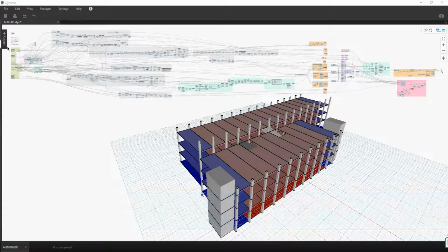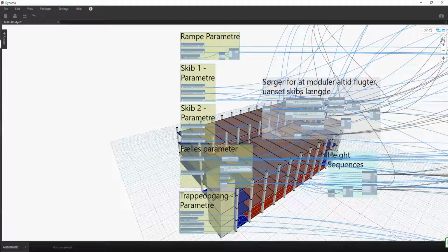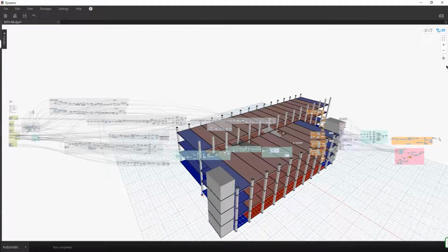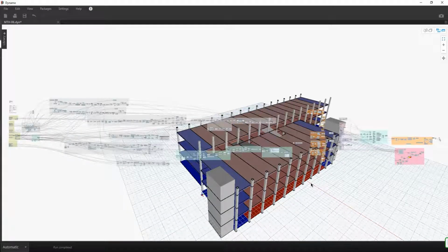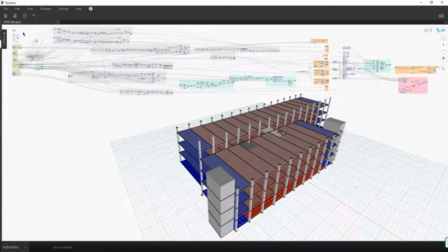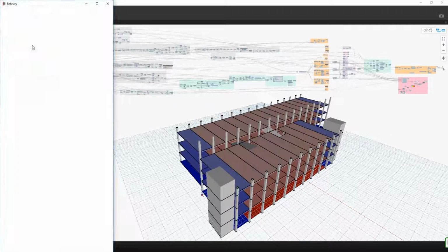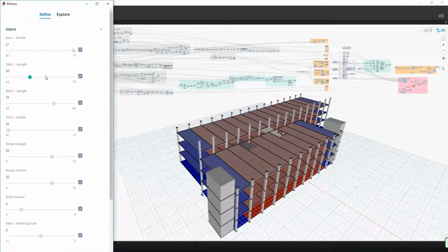In this parking garage optimization study, there are a series of inputs for the ramps, floors and structure as well as goals for parking space counts and an overall estimated cost of structure. Using Refinery, we can test structural lengths and widths as well as ramp length and position to deduce the garage with the greatest return on investment. Designs shift visually as options are tested.